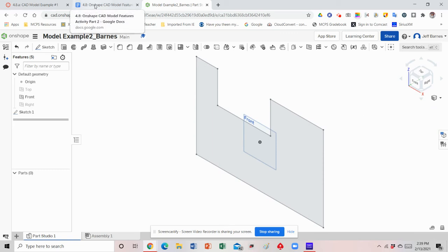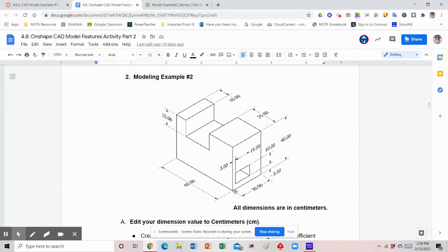And so I'm going to go ahead and look at my extrusion. So what is the depth of my figure? So the depth, again, is from the front edge to the back edge. And notice here on the right side, you can see what that depth is. So that's 30. So I'm going to go back and extrude it 30.